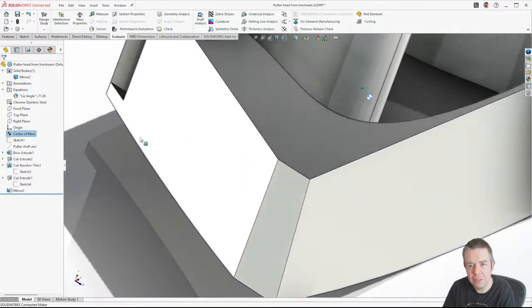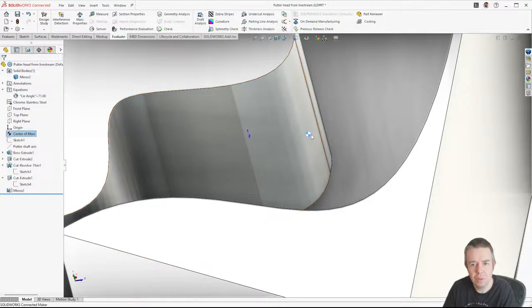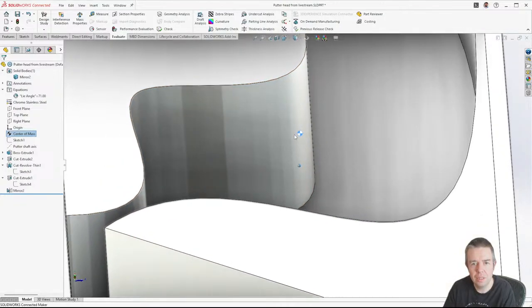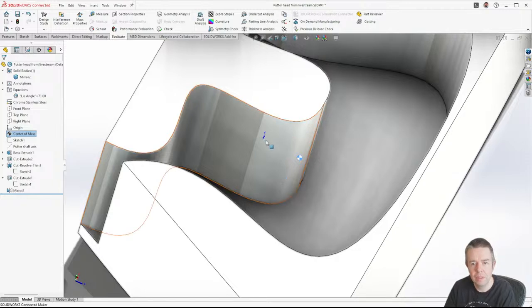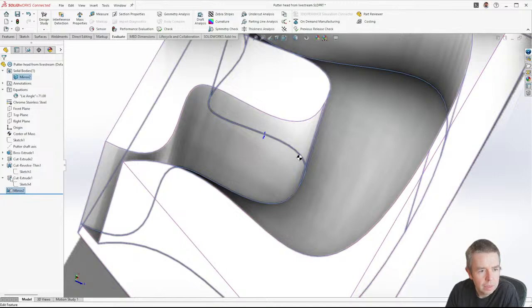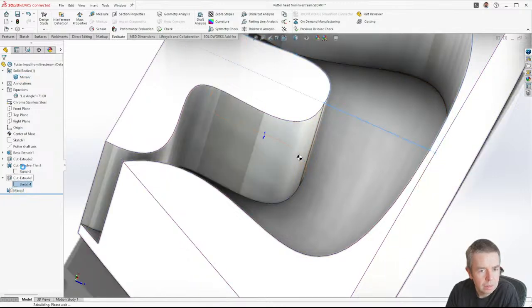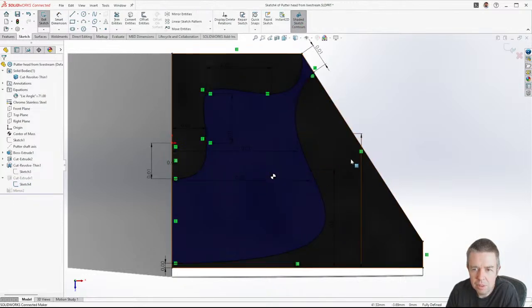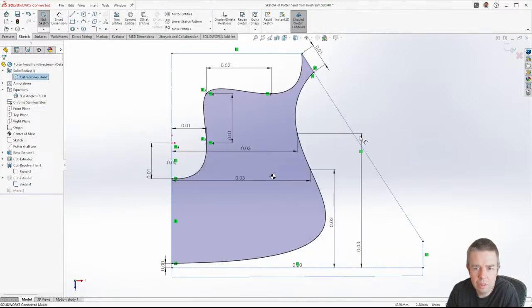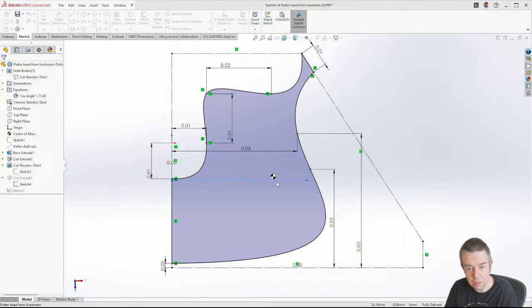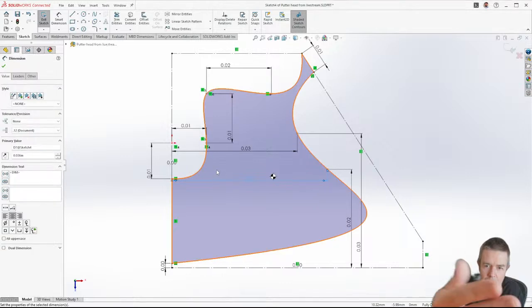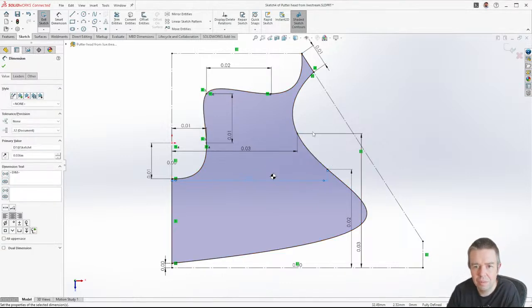And our center of mass feature is way forwards of our target, which was to have it in the origin. So we can mess around with that by messing around with these sketch constraints. Put more weight in the back part and less weight in the front part.